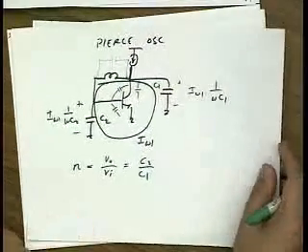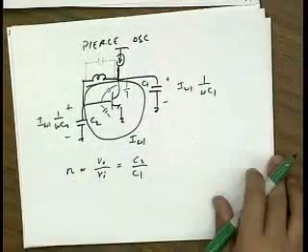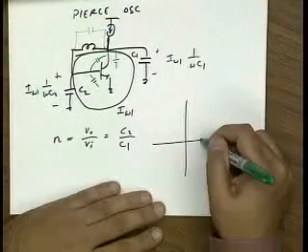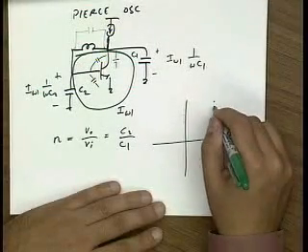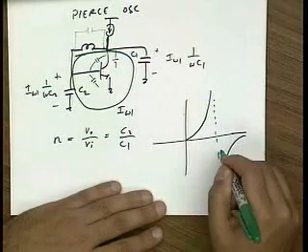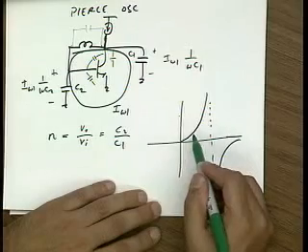The capacitance varies over the cycle because the voltage changes on the collector. Well, so basically if I have an LC tank and I look at the perfect LC tank, this is what the reactance looks like, right? So this is resonance. So as long as I'm below resonance, the thing looks inductive, right?